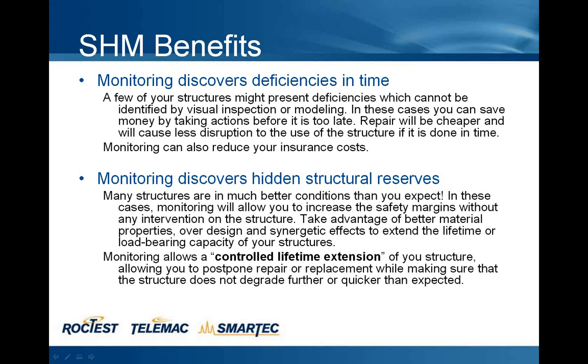Also, for structures that are insured, the monitoring can reduce the insurance cost because, again, it reduces unknown and risks associated with the structure. In many cases, quite the opposite happens, so structures are in better condition than expected, and in that case monitoring allows to increase the safety margin without actually doing anything on the structure itself except monitoring it. So this can lead to take advantage of better material properties, so maybe your concrete has higher modulus than was used in the calculation.